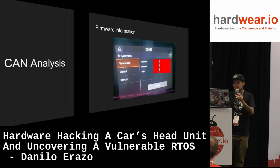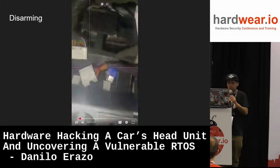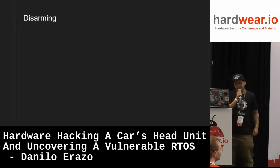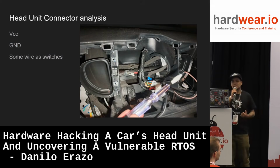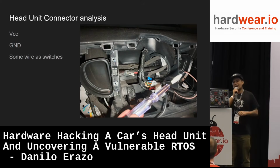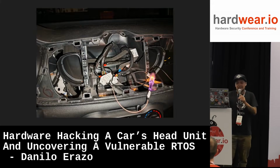Okay, go ahead. First of all, the information gathering, firmware information. No worries, I'm going to show the versions in a few slides. Here's the backside of the head unit. Okay, so we can see here the power connector, the CAN connector, the parking lights, the USB connector, and the antenna that is for the radio. Okay, so here I was able to identify in the power connector which pins are the VCC, the GND, and so on, what acts as switches, as you can see. In this case, to power on the head unit without the car.